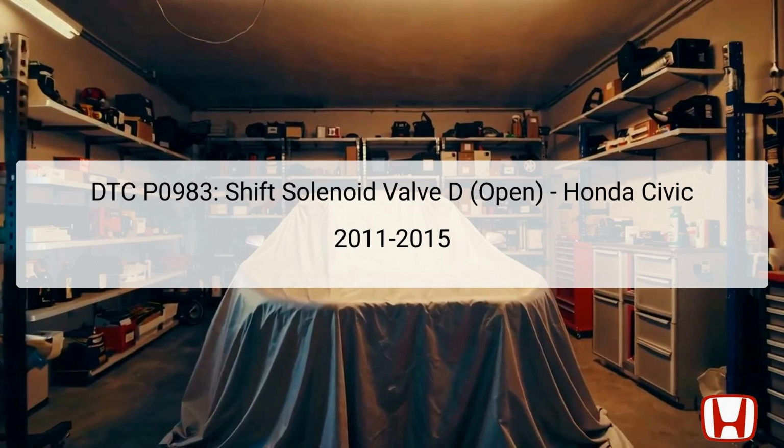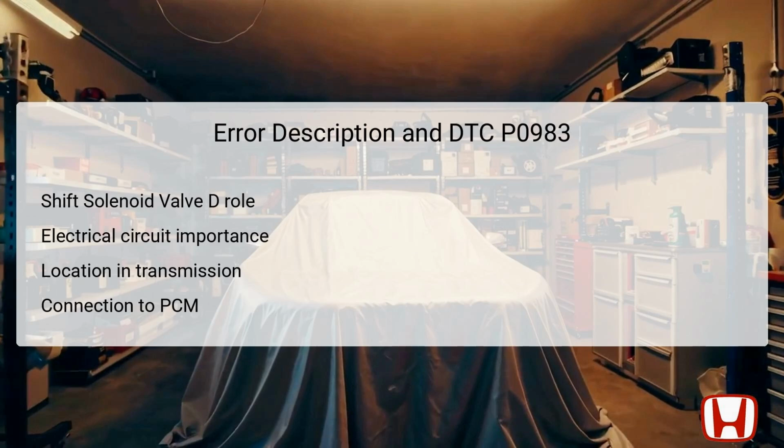As part of the diagnostic process, both freeze data and onboard snapshots should be recorded using the Honda Diagnostic System, HDS, to collect necessary data before proceeding. The shift solenoid plays a vital role in managing gear shifts. If malfunctioning, it can lead to shifting issues in your vehicle. It is important to note that this DTC cannot be attributed to mechanical issues within the transmission itself, which simplifies the troubleshooting checklist. The Shift Solenoid Valve D is an important component of the transmission system in your Honda Civic,